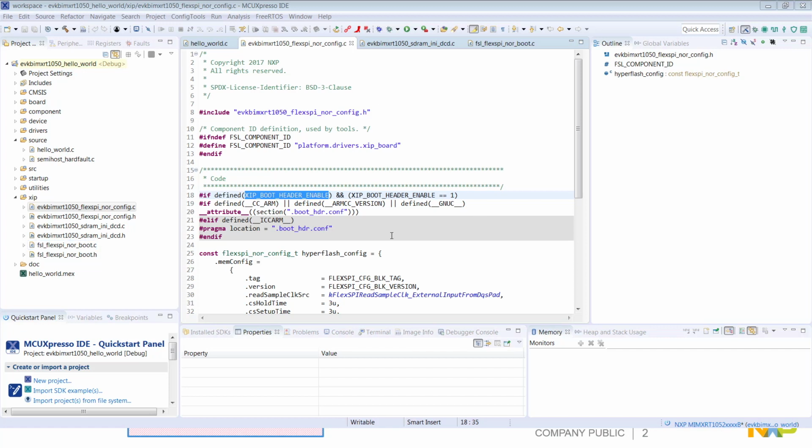Each of these files has defines that determine whether the boot data structure in question is included in the application or not. You can use the preprocessor define section of the project settings to include or exclude all of these boot data structures. If you want to run directly from the debugger and have a bootable image, you'll want to leave all the boot data structures in. If you are using some of our ROM boot tools, you may want to take these data structures out and have the boot tools add those files back in for you.